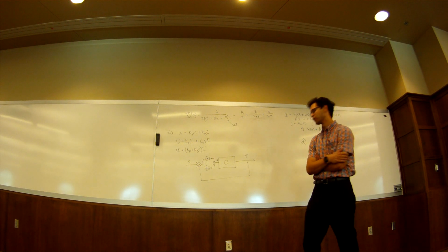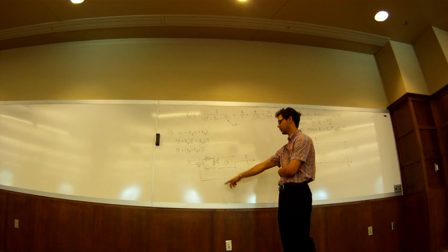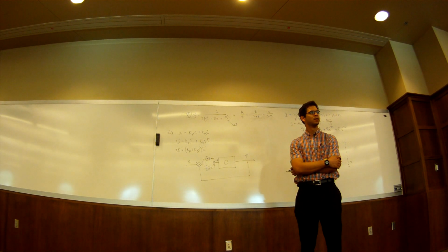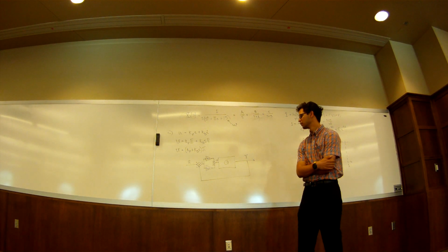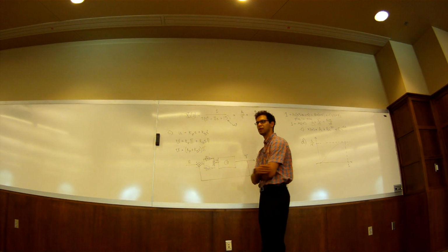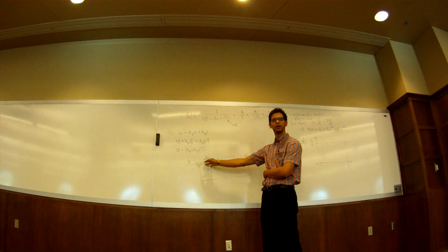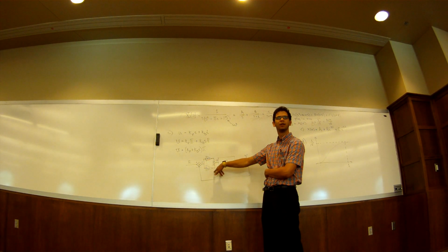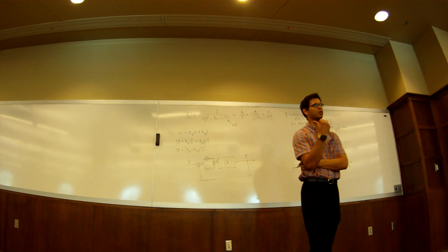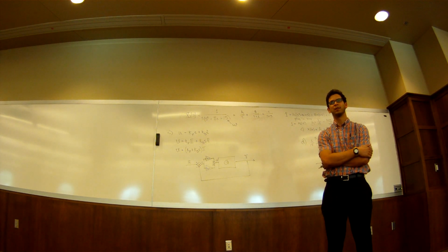I tried to give you points for getting the output, the transfer function, the unity feedback, and so forth. So there were a lot of 40s and 60s and 80s. What's that thing by the U? Is that a summation block? Yeah, that's a summation block. You take KP and KD S and add them together. What is this? This is cascade, parallel, unity feedback: parallel, and then these are in cascade, and then this guy, unity feedback. So when you reduce this block diagram down to one, you have to use all three special cases, right?